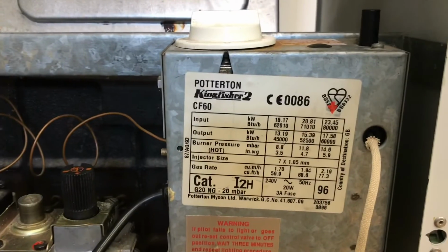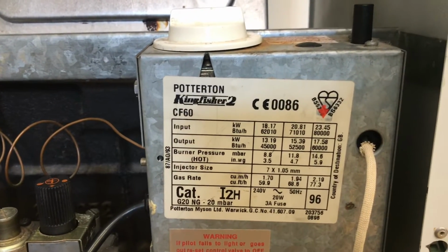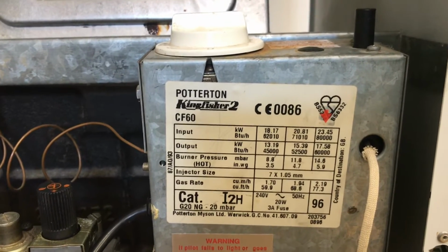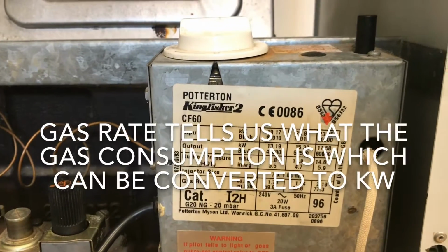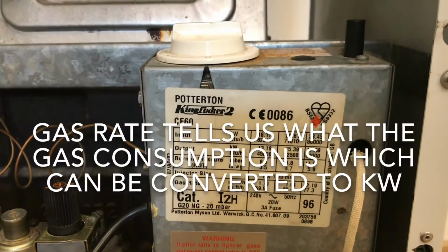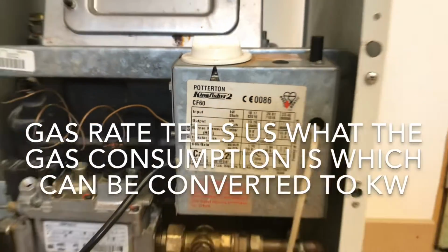This is a Potterton boiler. It's a Kingfisher 2, and if you look at the heat input, it's range rateable. Range rateable means you can have different settings and different outputs. But when we do things like gas rating on appliances, we'll always gas rate the input, not the output. So this is an 18 to 23 kilowatt boiler.